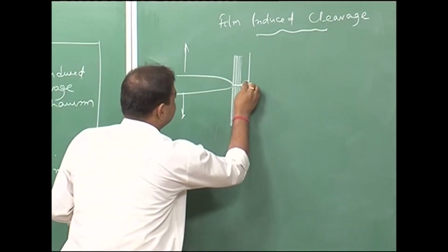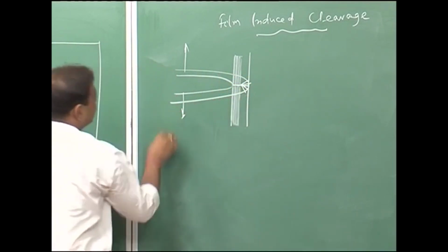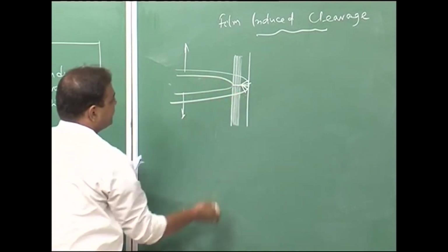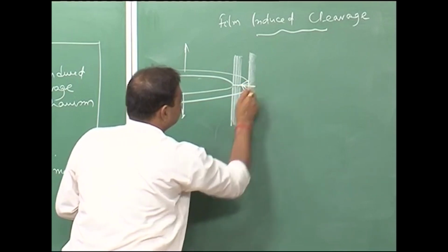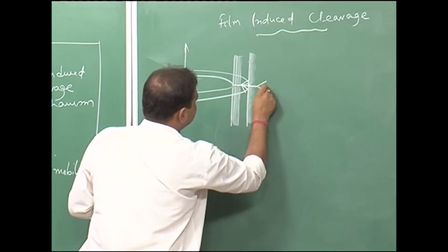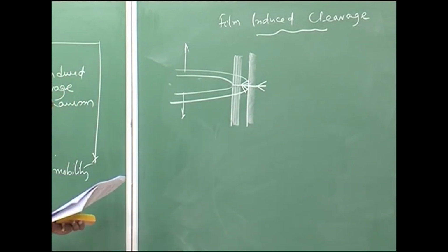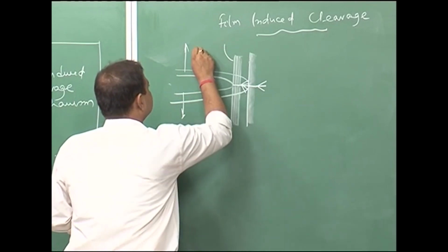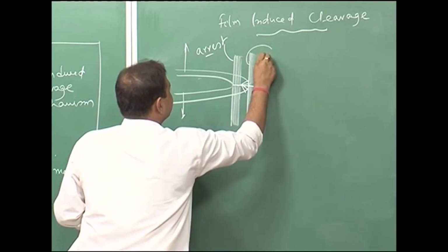So, then again here we have little extra growth, and then this crack is growing like this, and again you have passive film formation. Then again this sharp crack is propagating, and then again it goes to adjacent metallic volume. So, like that it moves on, and there you have crack arrest mark. This zone, this is another crack arrest,